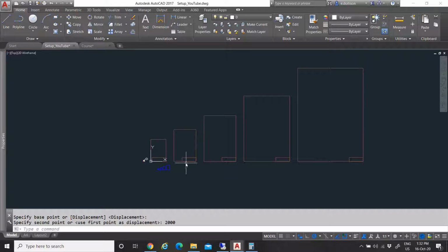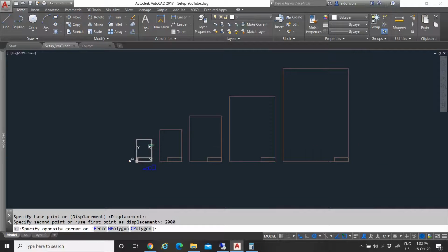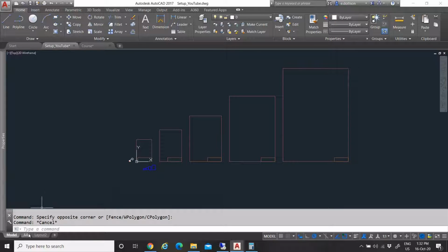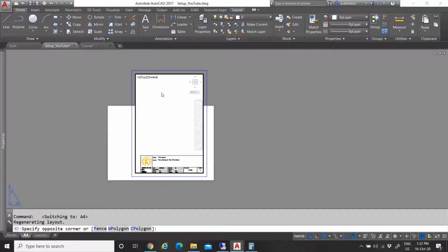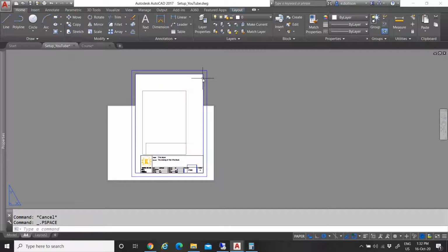You can place it wherever you want. I decided just to begin with this one, starting at 0, 0. And since I draw mostly medium-sized drawings, I prefer to use 1-on-20 as a starting point. So now let us go in our layout, and here we can double click in our viewport, and let's go to our A1, which is right here, help border.